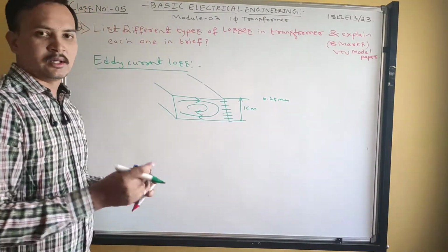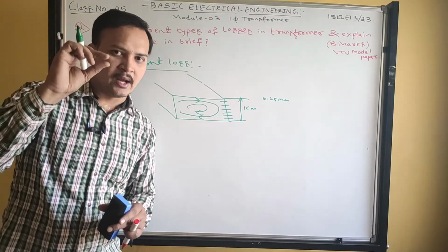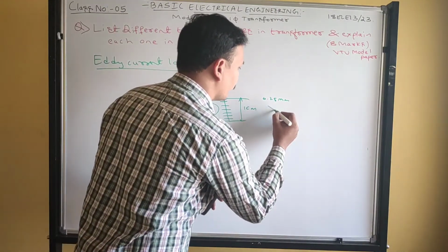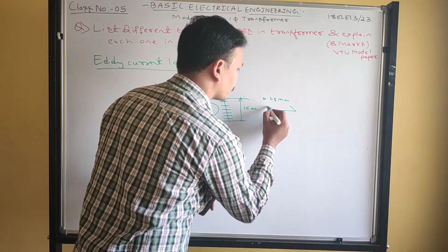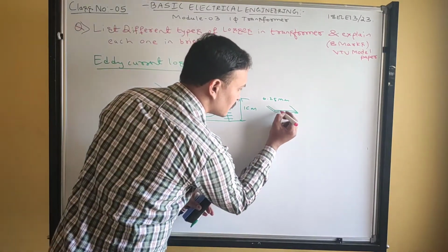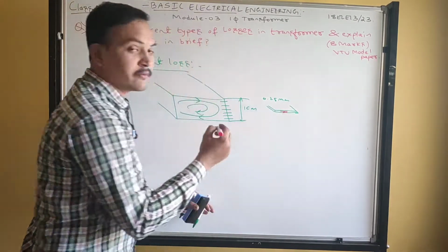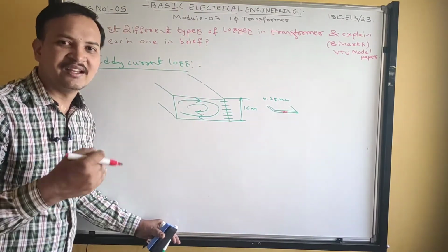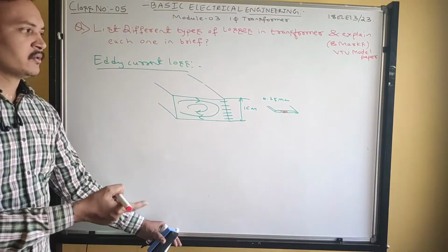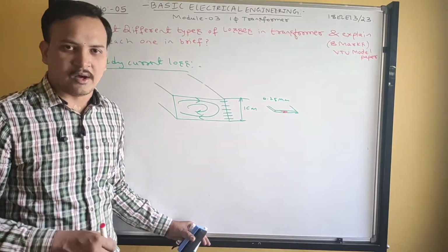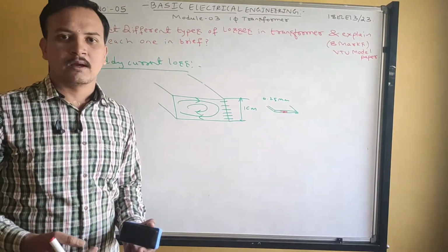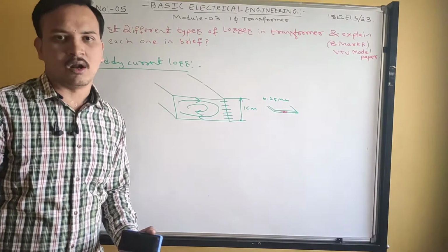Then it becomes a thin iron plate. Within each 0.25 mm plate, the circulating current keeps flowing, but that current will be very, very small. Okay, got it? By doing this, we can reduce the eddy current losses by increasing the number of laminations of a solid core.